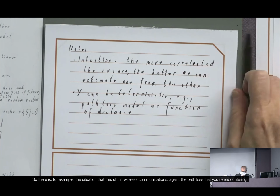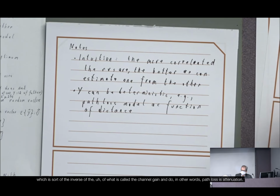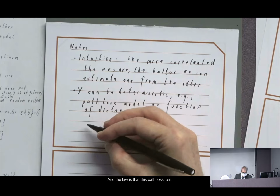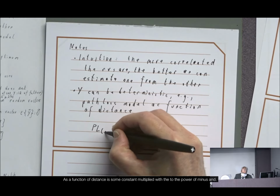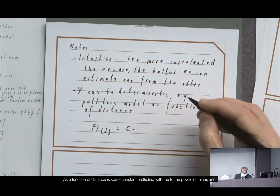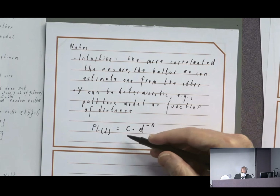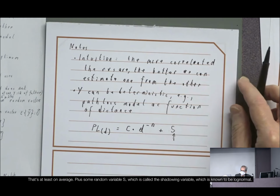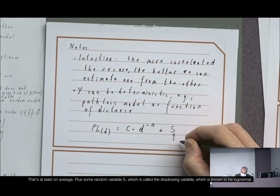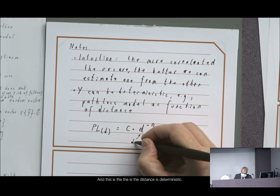There is, for example, the situation in wireless communications, again, the path loss that you're encountering, which is sort of the inverse of what is called the channel gain. In other words, path loss is attenuation. And the law is that this path loss, as a function of distance, is some constant multiplied with d to the power of minus n, at least on average, plus some random variable, s, which is called the shadowing variable, which is known to be log normal. And d is the distance, which is deterministic.